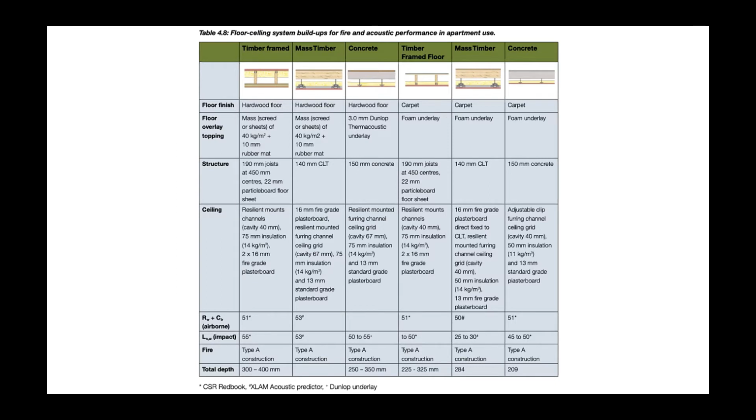So it's really important to understand the floor build-up for both acoustic and fire. For the fire performance, it's also likely that there's going to be a need for specific encapsulation, being a structural element that holds up walls.